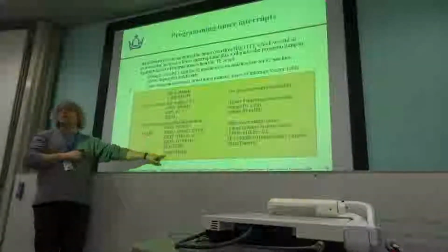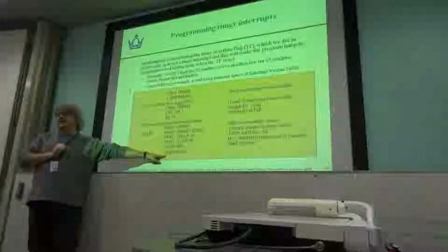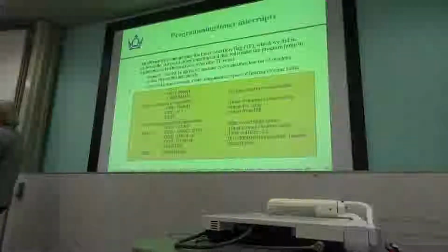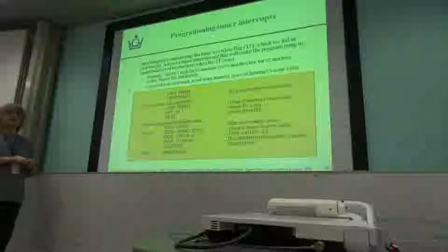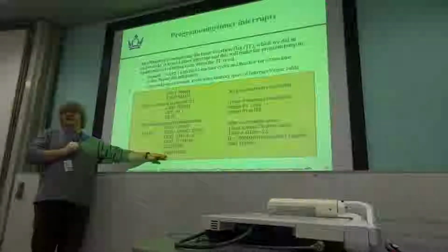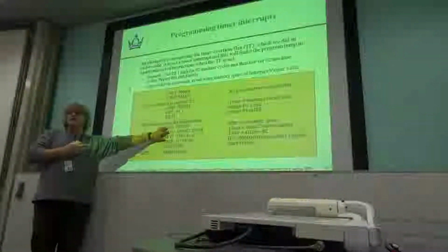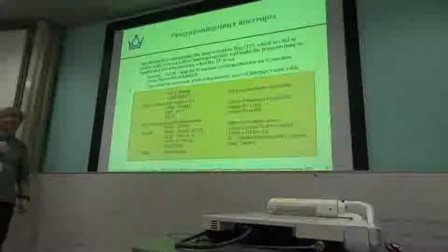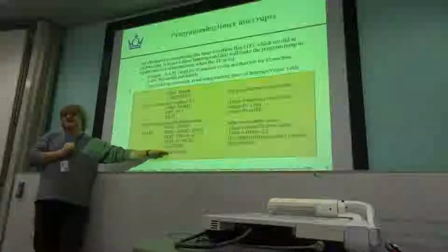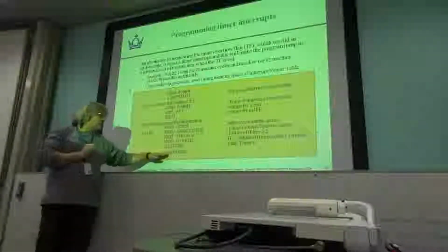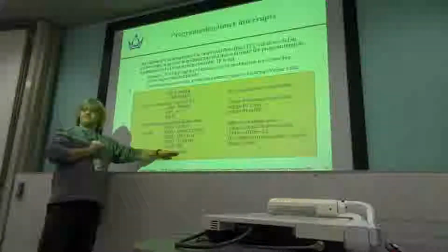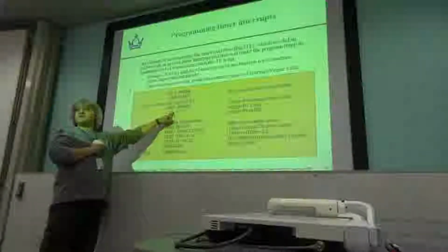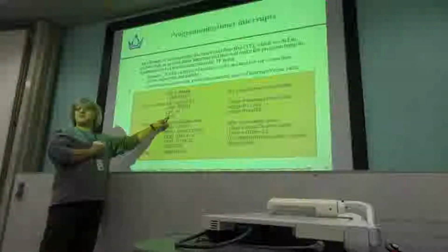You'll notice that there's no code here to basically check the TF flag, because we don't need to do it now. Basically, the interrupt hardware is going to do that for us. So we don't need to do any polling associated with the timer. We can get on and do other things. However, when that timer overflows and that flag gets set, that flag will automatically trigger an interrupt. We will then suspend the main program, and it will go to this memory location, flip this bit, and then return from the interrupt, clearing the interrupt flag.